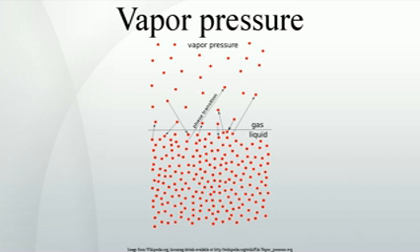-24.2 °C, which is where the vapor pressure curve of methyl chloride, the blue line, intersects the horizontal pressure line of 1 atmosphere, atm, of absolute vapor pressure. Although the relation between vapor pressure and temperature is nonlinear, the chart uses a logarithmic vertical axis to produce slightly curved lines, so one chart can graph many liquids. A nearly straight line is obtained when the logarithm of the vapor pressure is plotted against 1/(T + 230), where T is the temperature in degrees Celsius. The vapor pressure of a liquid at its boiling point equals the pressure of its surrounding environment.